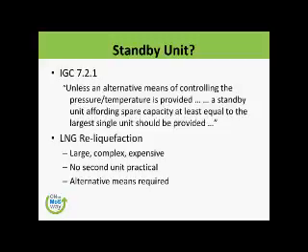Unless an alternative means of controlling the pressure and temperature is provided, a standby unit affording a spare capacity at least equal to the largest single unit should be provided. Okay, so a standby unit is also required. Means if you have got too much boil-off, then you should have a spare of more or less equal capacity. You can also burn the boil-off gas.